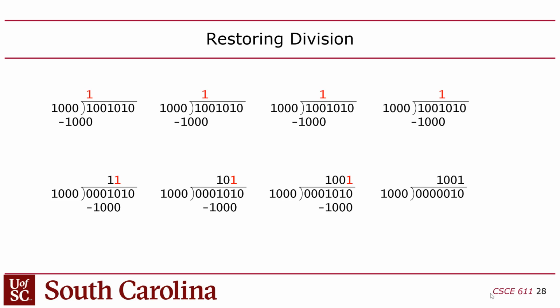Yeah, exactly. What does it do with 0 for the same reason? If you divide by 0, the hardware would have to have a catch for that. What you'd end up with is all ones, with a remainder of 74. This hardware design would give you a quotient of all ones, which would have been 7 ones, so 127, I guess. So it would give you a quotient of 127 and a remainder of 66, which the hardware would then have to catch as a divide by 0 error.